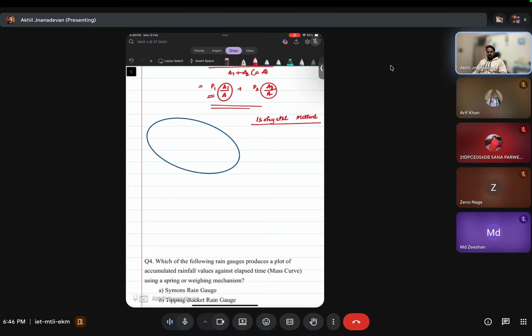The same principle applies if, instead of the same elevation, you make a map of the same rainfall. That is called the isohyets. These lines are like different contours, and each line represents one particular value of precipitation: P1, P2, and P3.